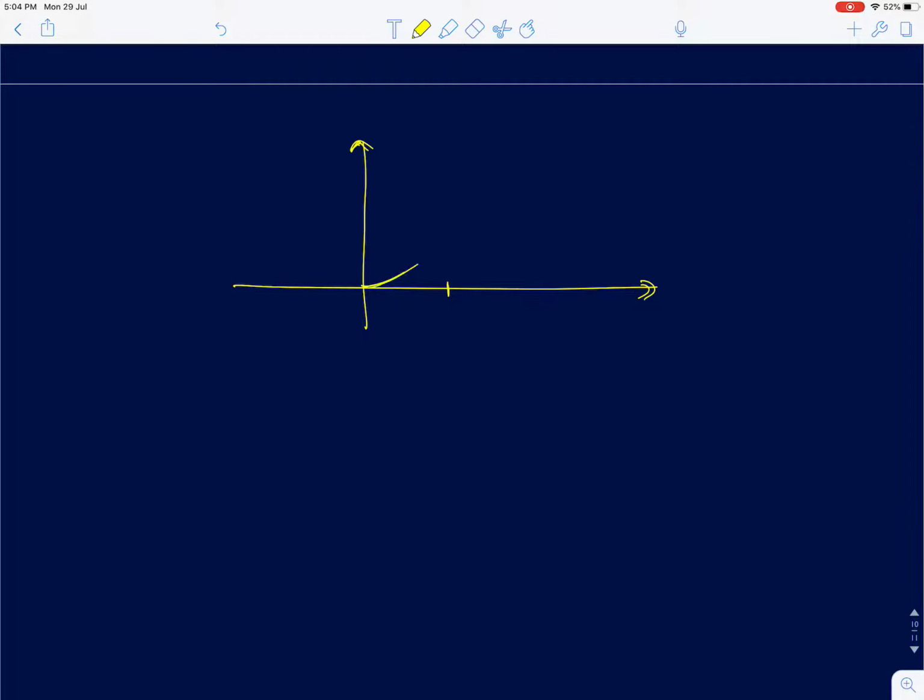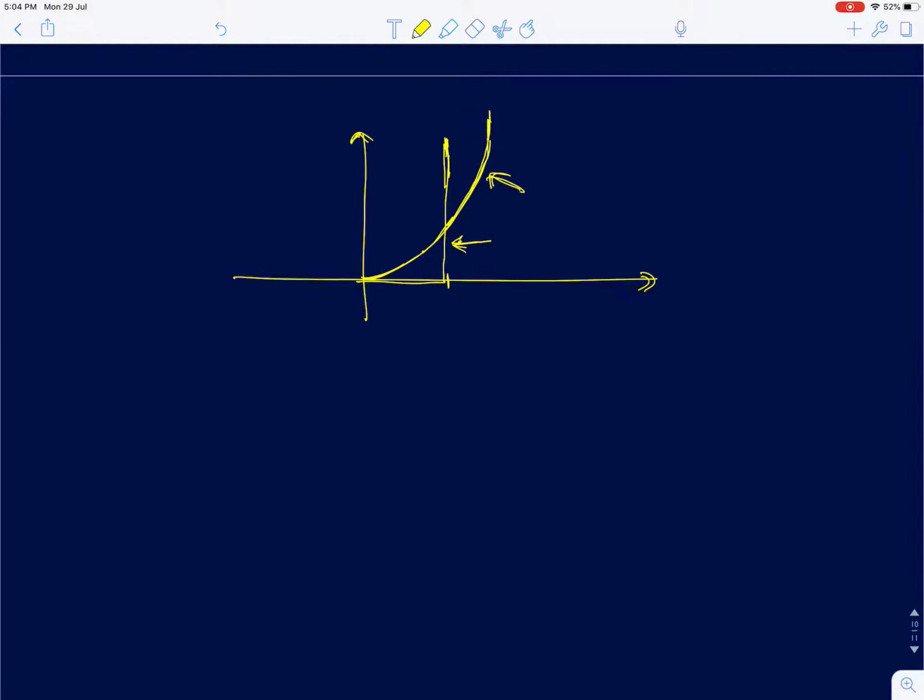So for example, what you're actually doing is that it's an exponentially increasing curve, and you're modeling it with a curve like this. This is the curve used in modeling, and this is the actual curve. Now if you look at it, as your current increases, the model is going to diverge significantly. You are always assuming the voltage is constant across it, but the voltage across the diode also increases significantly when your current increases. That is not captured in this model.